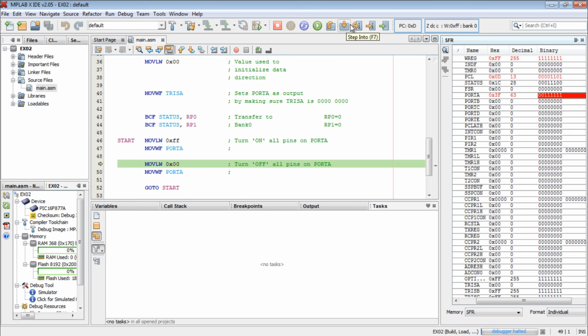So every time you read them, their values will be 0, regardless of whether you wrote 1 to them. So the system really doesn't care if you write 0xFF. Only 63 would remain, because only bits 0 to 5 would be changed, and 6 and 7 would remain 0.